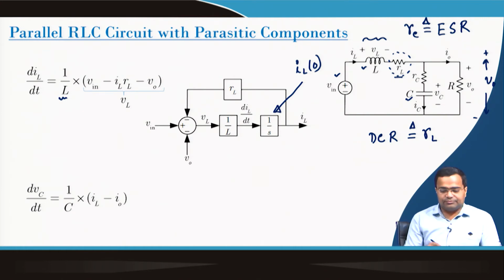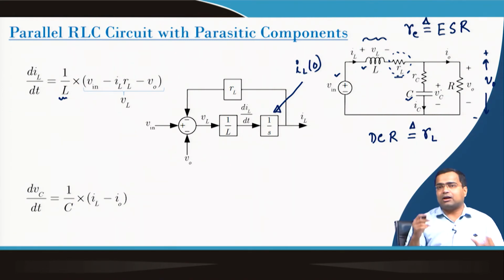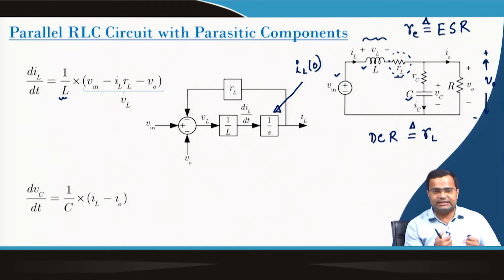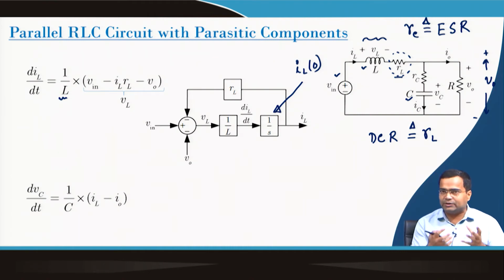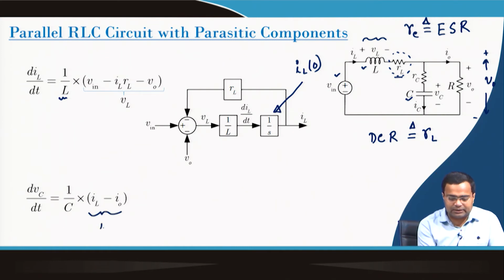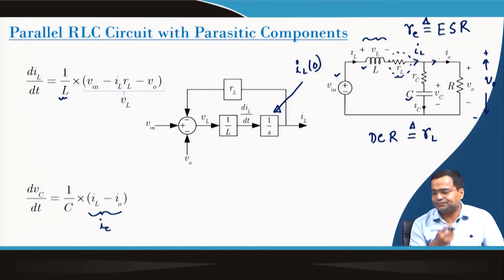We want to now realize the dynamics of the capacitor, and here we are talking about the voltage across the ideal counterpart of the practical capacitor. This derivative of the voltage, dVc/dt, is 1/C into IC, which in this case is IL, this current is IL and this current is I0, and this capacitor current is IL minus I0.